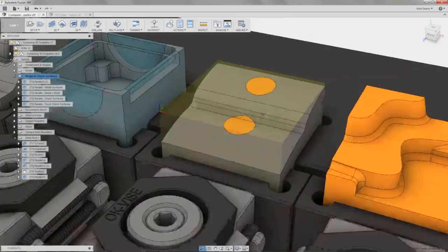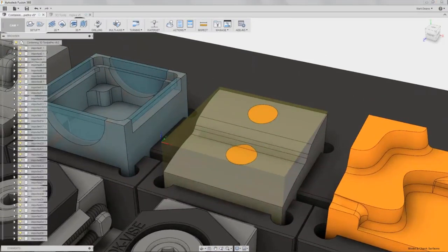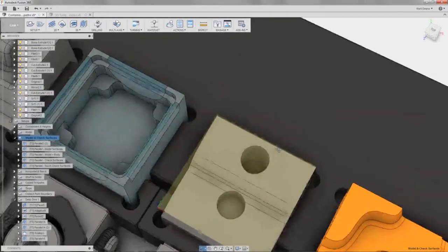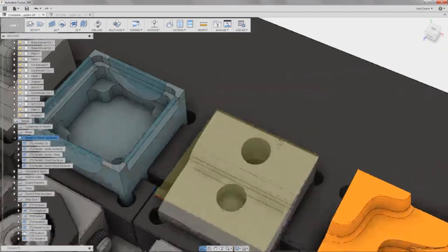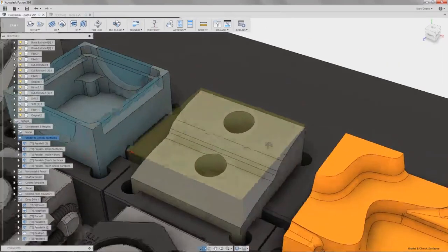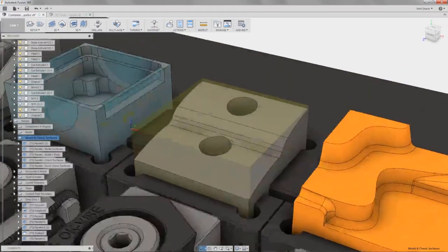So in this next part, I have this little gray guy, and he has two holes, and those two holes are covered by surfaces. So those are the holes. Let's say I've already bored them out and they're already cut, and now I just need to finish this nice smooth surface. So it's ripe for a parallel, right? Look at that, only changing in one direction. Parallel is going to work awesome.